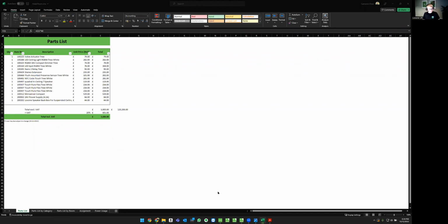Now, I touched on already ventilation and heating. Ventilation systems can tend to be quite self-sufficient. But if we know that a room is unoccupied, we can run the ventilation on its boost setting to make sure that the room is well ventilated and there's no stagnant air in there. And that can be easily done by utilizing the presence sensors and or time of day.